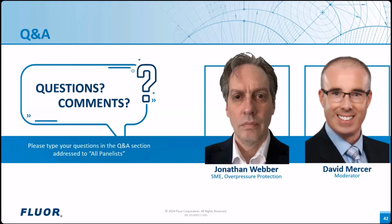to prevent the overpressure. The other case we see sometimes, and see happening more often, is that a PSV is not sufficient. It's sufficient to meet code compliance, but it's not sufficient to meet client risk tolerances. So while you may need additional instrumented systems to close that gap and meet the client risk tolerances, from a regulatory point of view, those instrumented systems are not necessarily replacing the PSV or reducing the relief load, so they're not in a regulatory sense HIPPS, but they're a critical part of an instrumented system working in conjunction with the PSV to meet client risk tolerances.